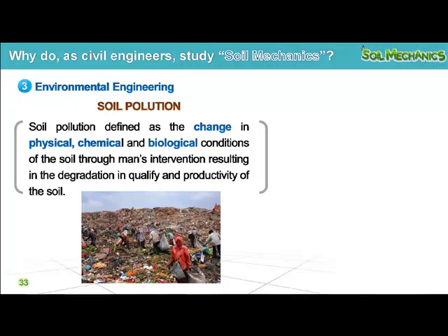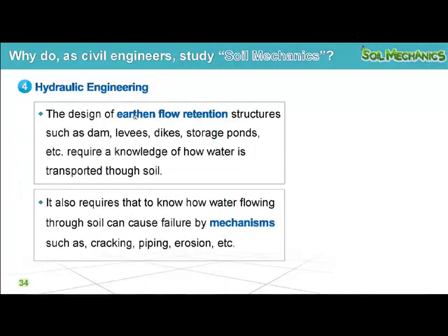Hydraulic engineering. About hydraulic engineering, the design of earthen flow retention structures such as dams, levees, dikes, storage ponds, etc., requires knowledge of how water is transported through soil. Yeah, I mentioned before, how much it can flow through soil, how fast. It also requires knowing how water flowing through soil can cause failure by mechanisms such as cracking, piping, erosion, etc.